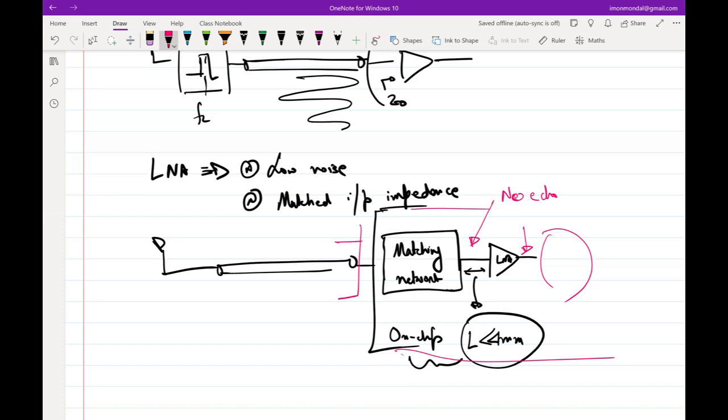It is connected by a transmission line in the PCB at the input. It is connected to a transmission line at the output also. Then what do you need to ensure? The output of the LNA also matches to the transmission line. If it's an off-chip LNA, you have to ensure both the input impedance and the output impedance are matched, because they are driving an external environment which is not in your control, right? But if it is inside the chip, you need not bother, as long as the transmission line effects can be neglected. Okay, another important design takeaway, right? Because this can have design implications, if you know that whatever the LNA is driving is in the chip, you do not have to bother about putting in extra brain power to match, right? If it is off chip, then you need to.